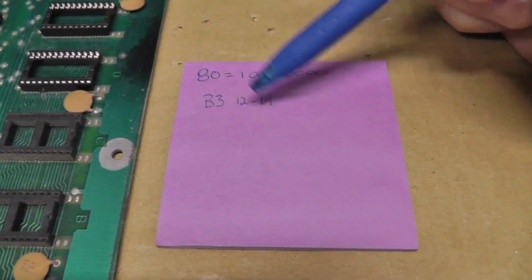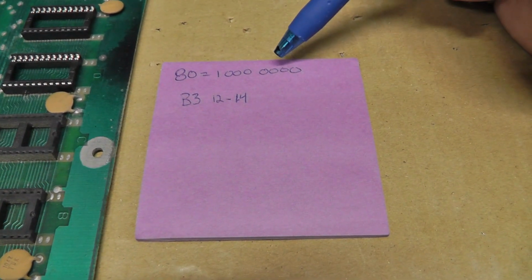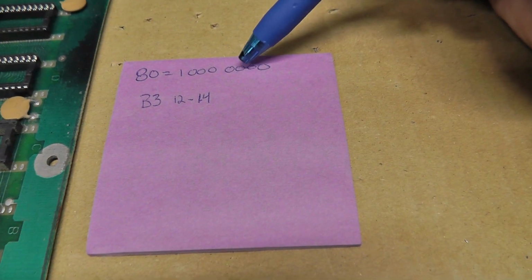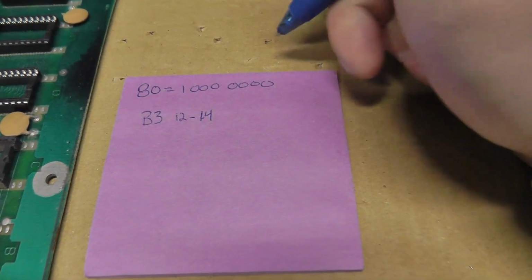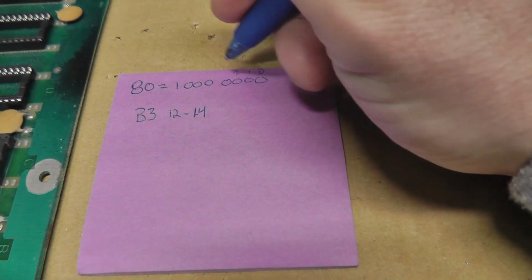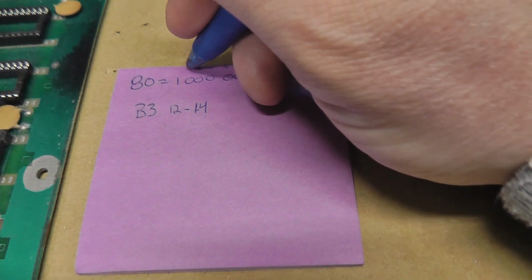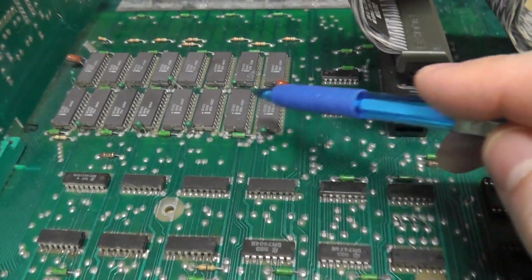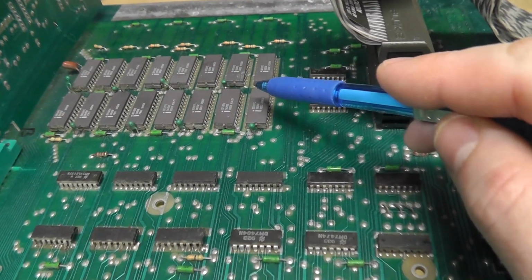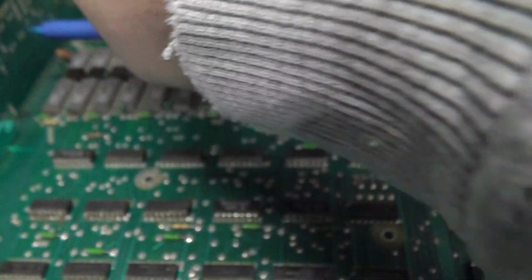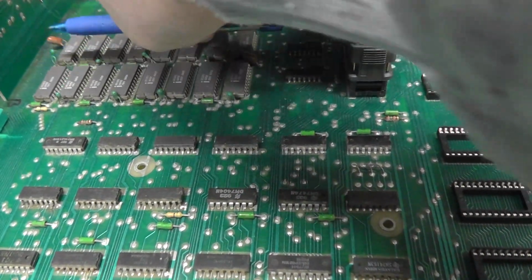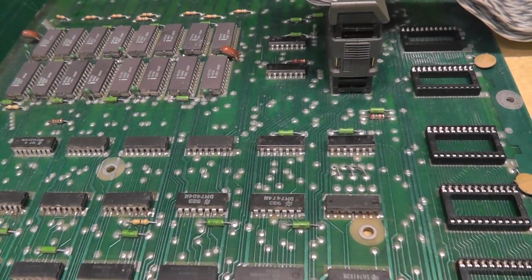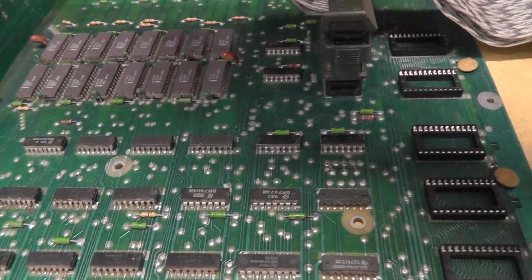Okay, so based off of the last video, we know that the hex of 80, that bit mask, is 10000000, and this is basically data line 0, 1, 2, 3, 4, 5, 6, 7. I showed this in the previous video, but this is this grouping of chips. One bank operates on even addresses, and one bank operates on odd addresses. But the same data line is shared between these two chips.